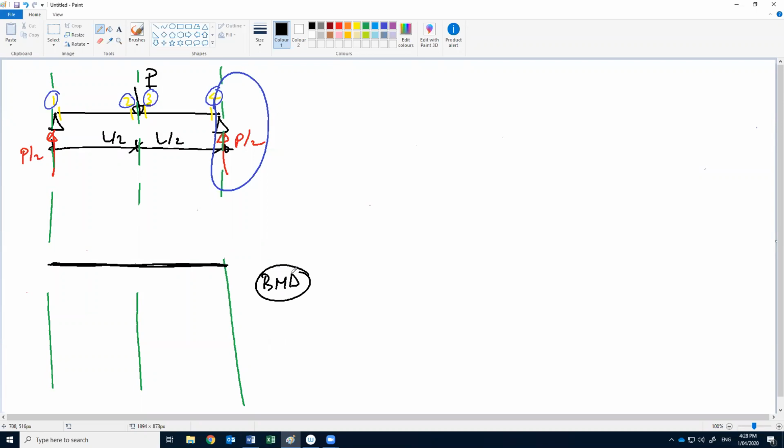How to draw the bending moment diagram for this beam? We will start the same as we start in shear, with section 1 or cut 1. What causes moment at section 1? Is there any force causing moment, or is there any moment at 1?